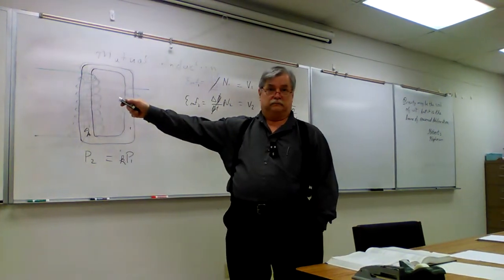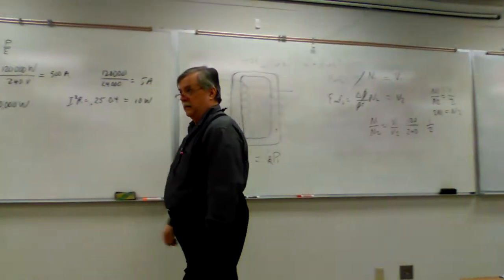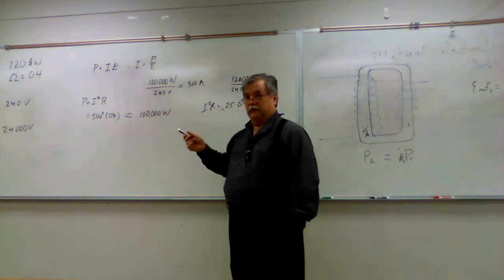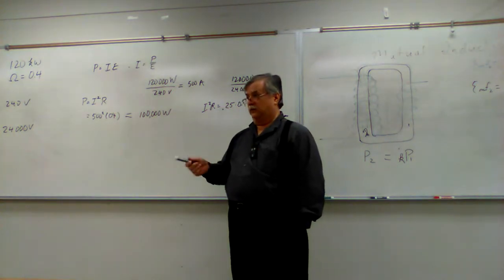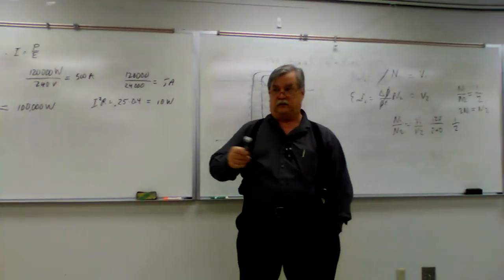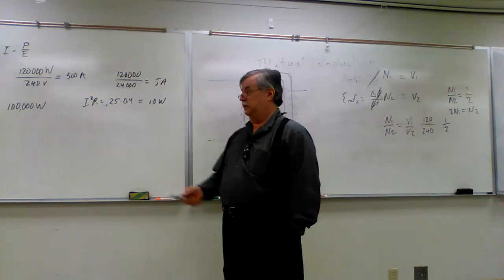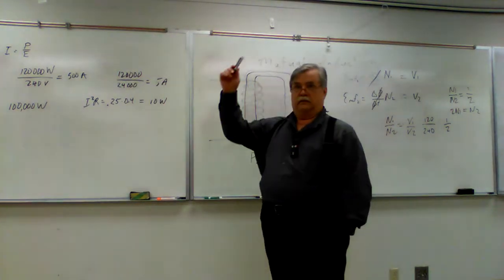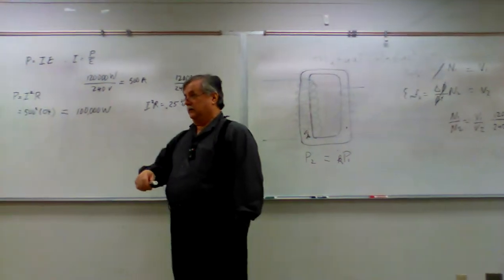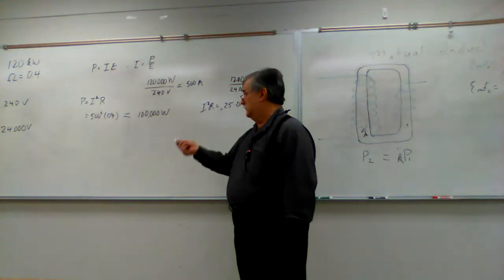This is why. You're pumping in the same amount of power, you're getting out the same amount of power, but the power that you're transmitting is not the source of the losses. The source of the losses is the heat generated by the current. That's the beauty of a transformer. Crank up the voltage, the current goes way down, but the power across stays the same, or very nearly the same.